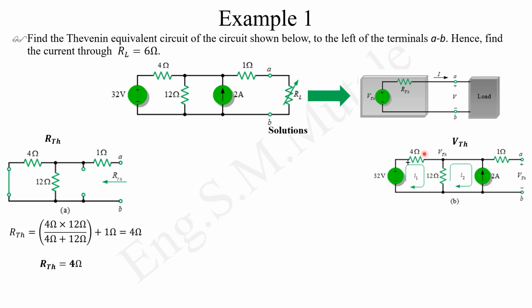I was saying in this loop, you assign polarities to the elements which haven't been given polarities. So if you look at the voltage source, which is this one, it has polarities, you leave it. You come to this one, it doesn't have polarities, so you give polarities going in the clockwise direction. The terminal you meet first, you give it positive, then the other one negative. So this one will be positive and that one negative. When you reach this one, you give it polarities positive and negative.